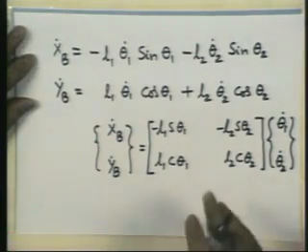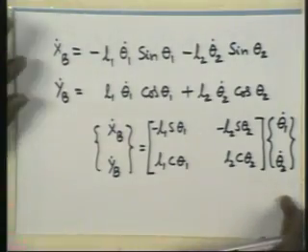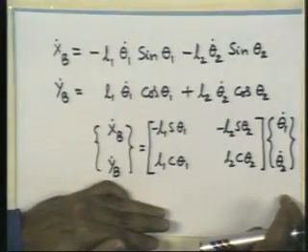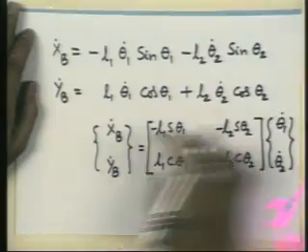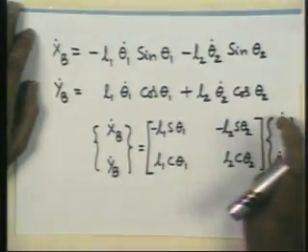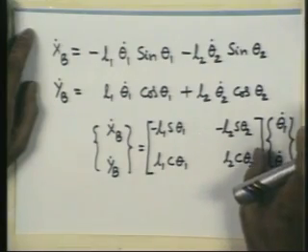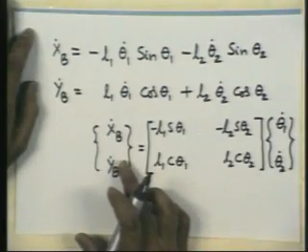Okay. So, here again, if you look at the equation, the problem statement would be in the following manner. I want the end effector tip or the robot manipulator joints to move through a particular position with certain velocity. So, the position information is already known when I talk in terms of velocity information. For a given position, theta 1, theta 2 being known, if you are given theta 1 dot and theta 2 dot, to find x b dot y b dot is a straightforward, again, linear algebraic equation. Matrix multiplication will give you this x b dot and y b dot.